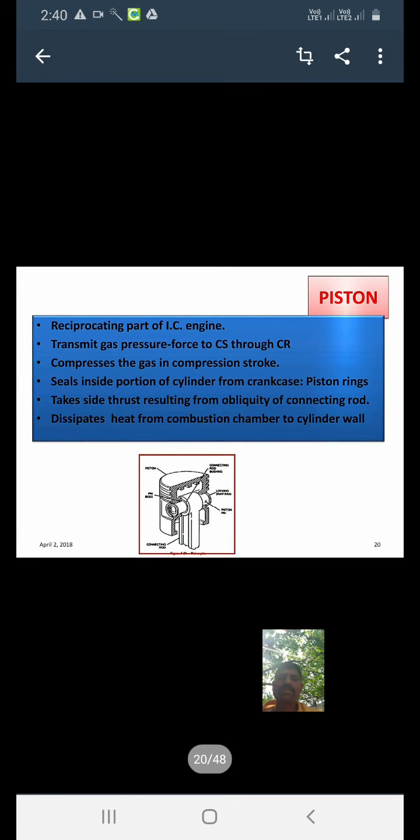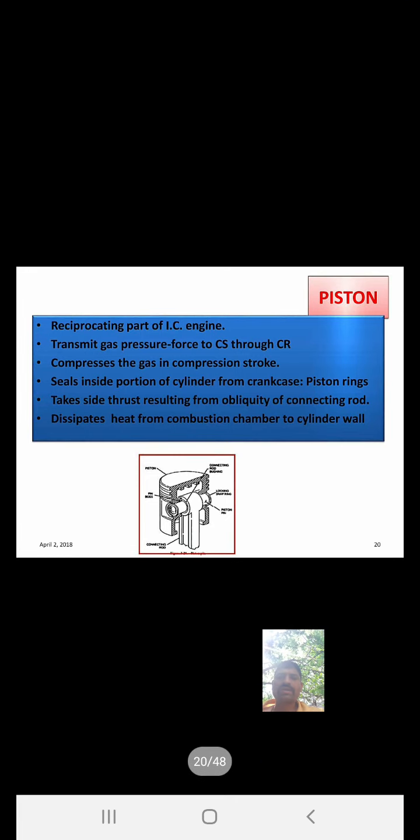Then what is the use of the aluminum alloy in the piston? Okay, the strength of the forged aluminum alloy is 40% higher than the aluminum piston made by casting. Okay, then forged aluminum pistons are used for heavy duty pistons, high speed engines, and for aircraft, and for high power engines also. With piston speed above 6 meter per second, then we want to use the aluminum alloy material.